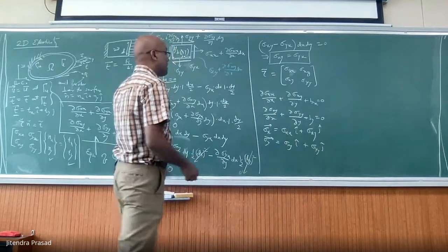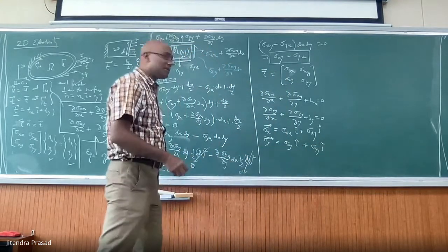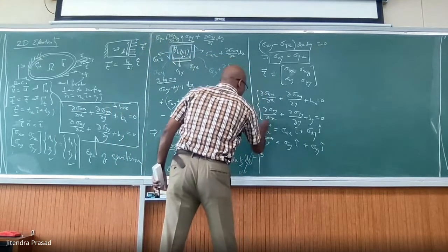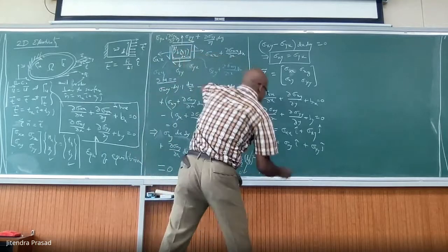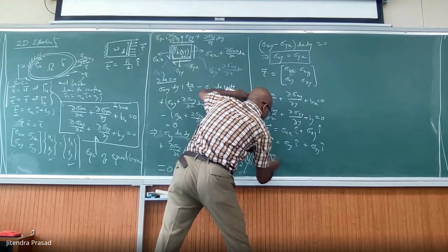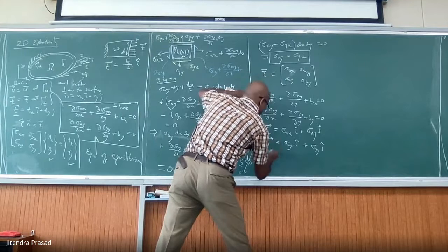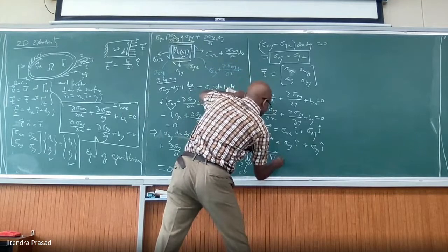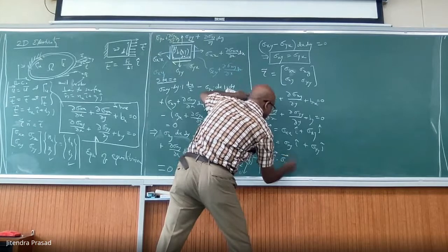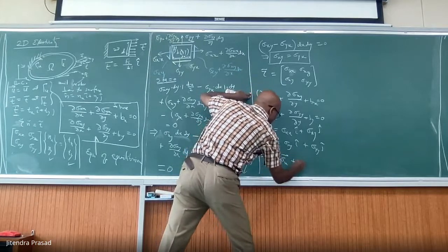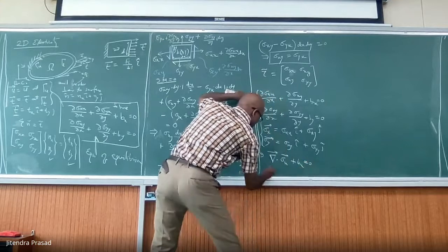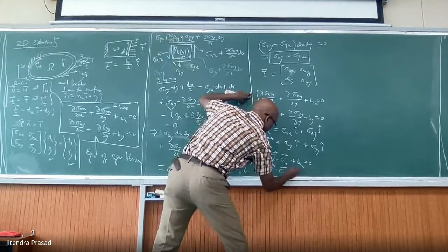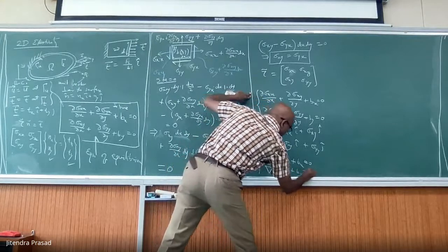Now these can be written based on this. We can also write them in terms of divergence, and we love divergence. You can write this as divergence of sigma x plus bx equal to 0, and divergence of the sigma y vector plus by equal to 0.